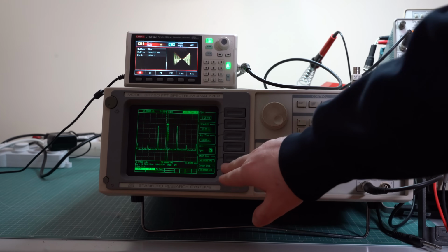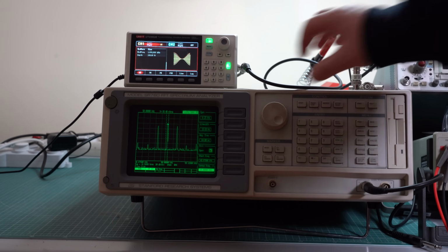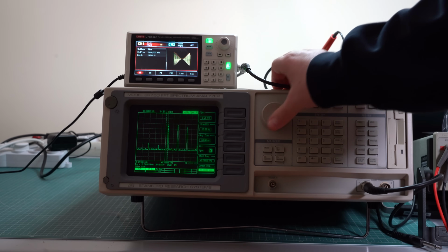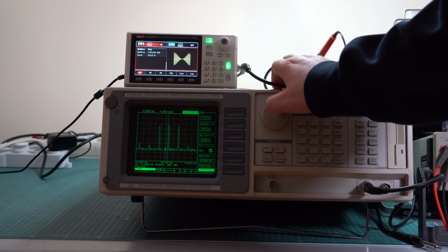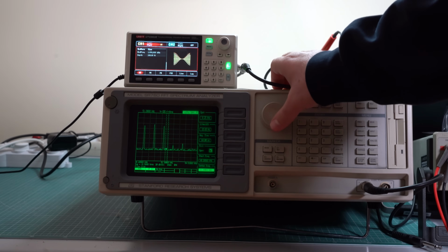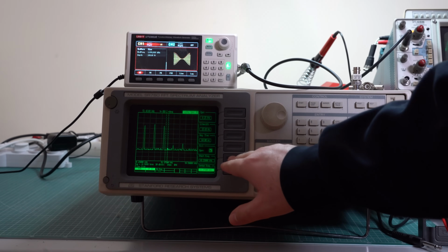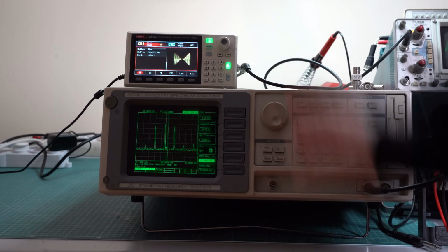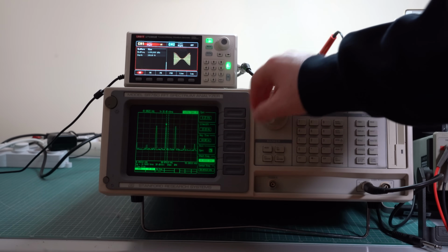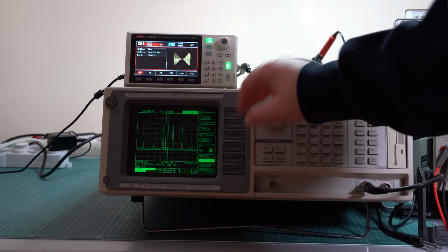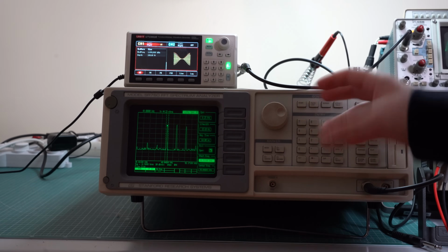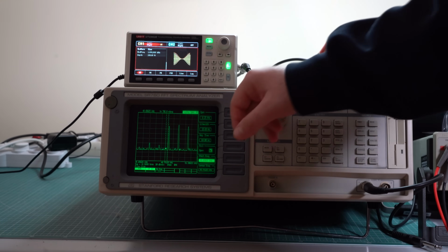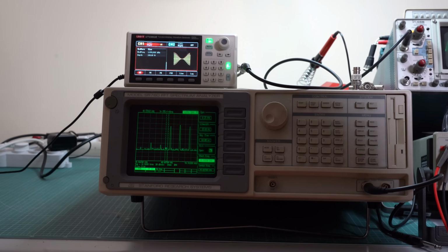Another important setting is the center frequency. By selecting it, you can obviously offset your center frequency in case you want to look at something else. You can go both ways, of course, and this spectrum analyzer also allows you to set it in a different way, basically by setting the start frequency instead of the center frequency. The start frequency is of course the frequency that you have at the left of your graph. You can also adjust it, and since the span is fixed, it just moves together with the center frequency, which is a bit strange and counterintuitive, but this is how this instrument works, at least.